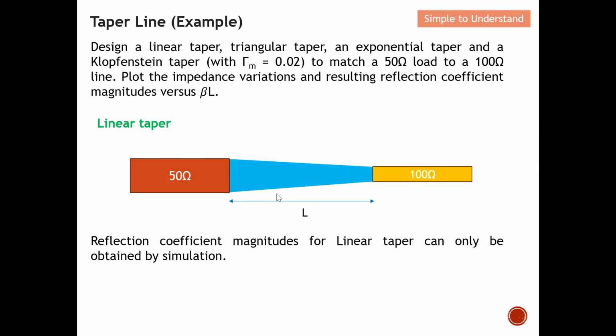This will be a tapered line for impedance transforming. So basically you have done this impedance matching through a linear taper line. In short, there's no formula. What you need to do is draw this to reach the other side, and on the other side also draw to reach the other side. What you can only control is the L.